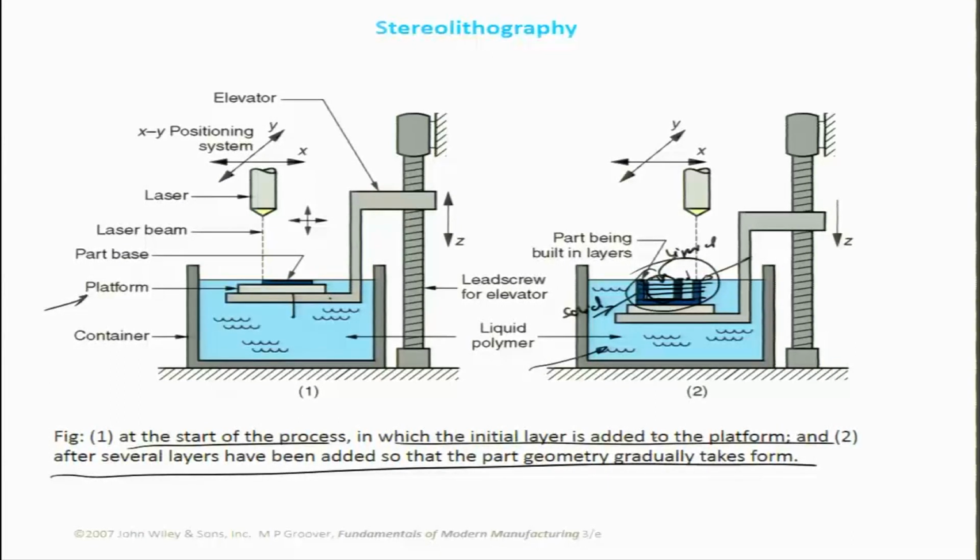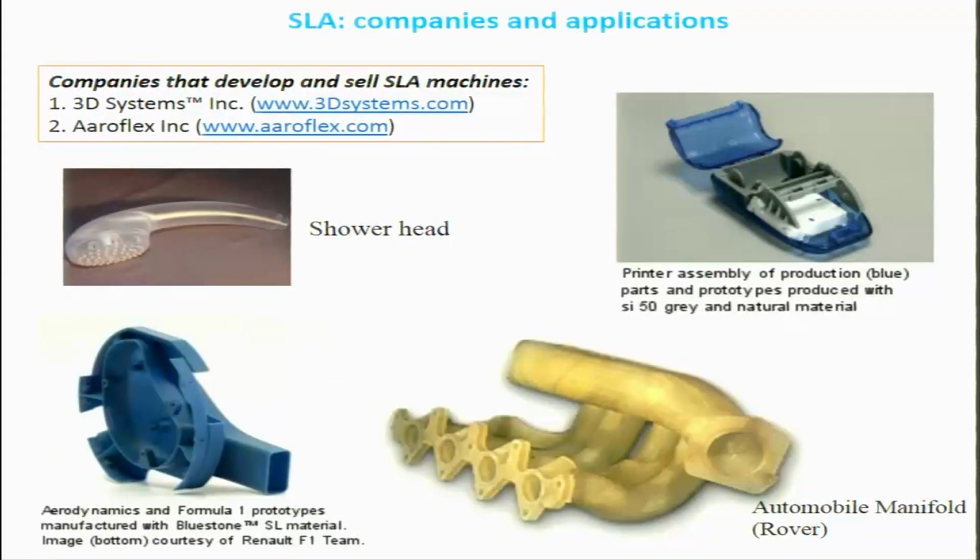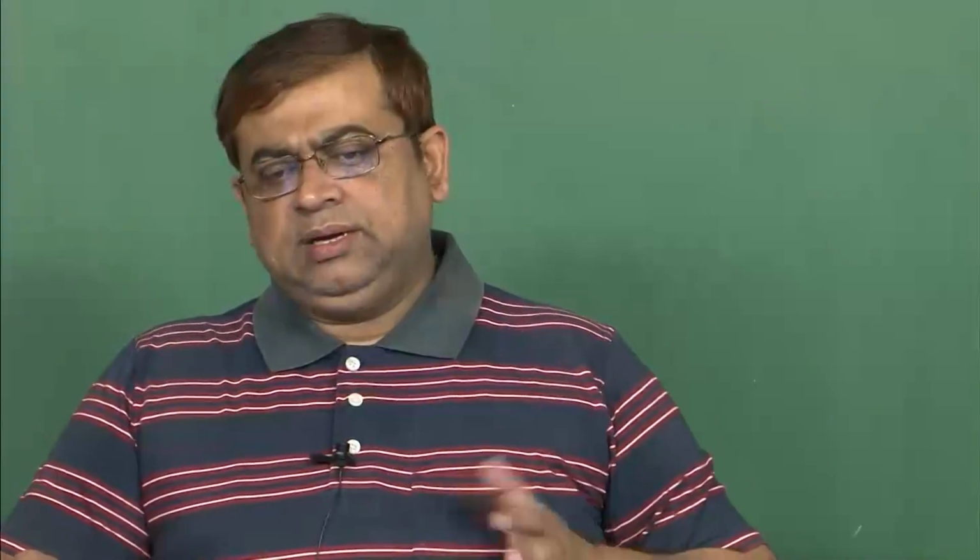If I looked at what this resist was and how it would behave, there are many details which I have covered in my past lectures, particularly when we were talking about MEMS based sensors, where we detailed how there can be classification into positive resist and negative resist, and what is the chemical principle behind a weak acid liberating protons so that it participates and cross bonds, creates a three-dimensional network of bonds, and then you could remove the areas which are not bonded so well and which results in a solid structure.